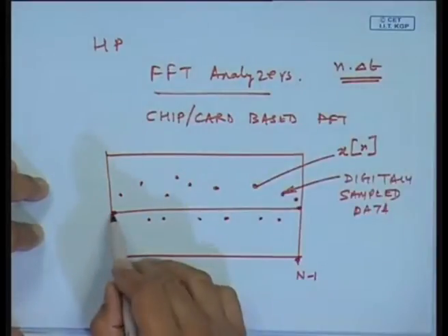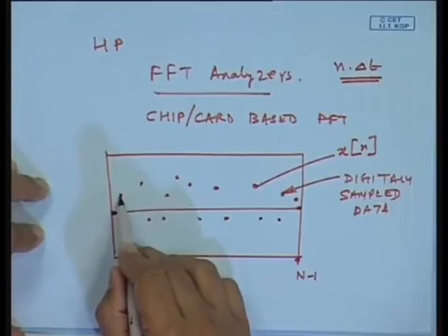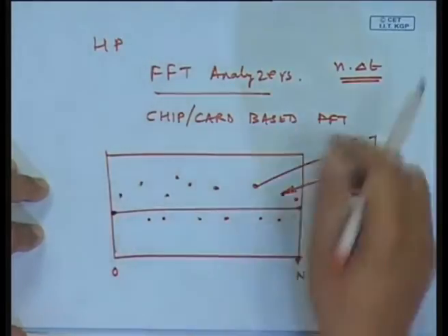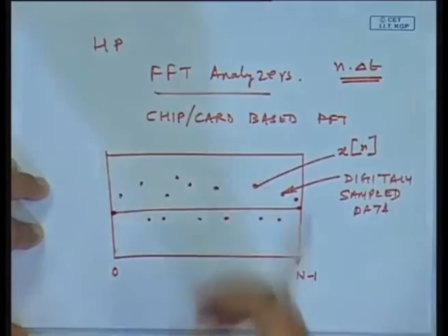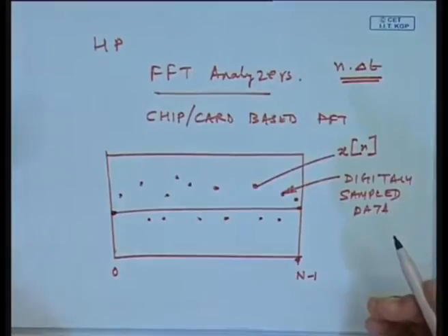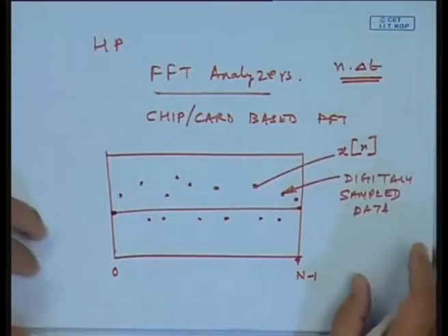So, I will take n equal to 1 times delta t, 2 times delta t, 3 times delta t, and pick up all these successive values and plug them into the equation of DFT, do the operations using either the n log n operations or the n square operations, and come up with components which will be nothing but the Fourier components of such a signal.